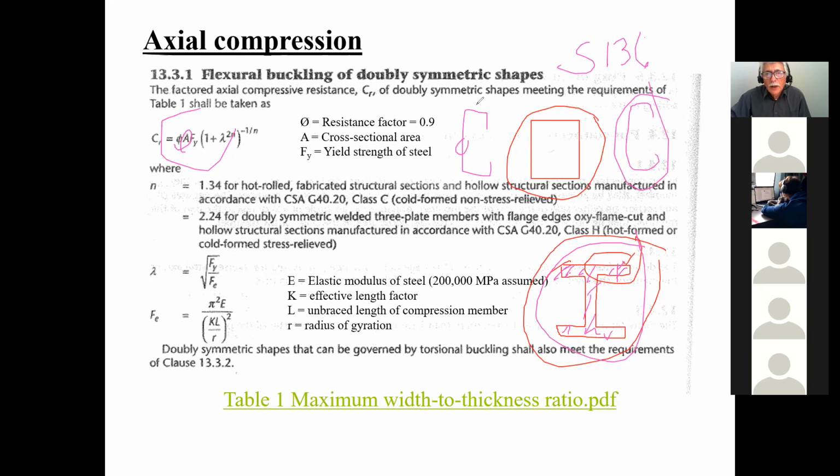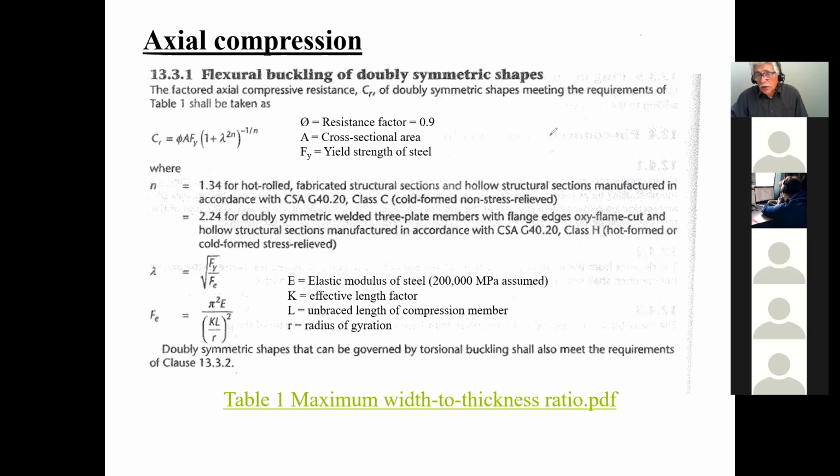So instead of me relying on this whole cross section here, I'm just relying on when one of these plate elements will actually fail. That's what I'm doing. And so keep that in mind. As soon as you start getting into a Class 4, you got to go to S136, because that's the standard that has all the equations for that thinness of material. Okay.